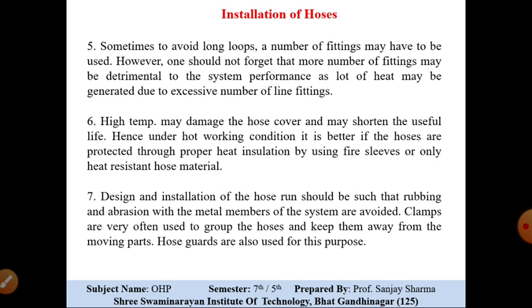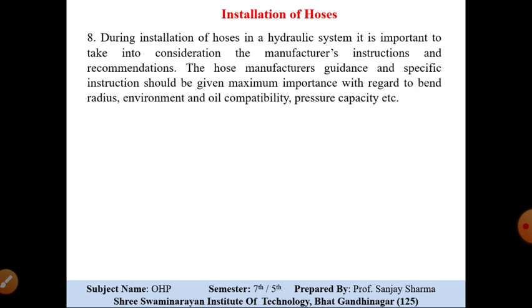So it should be kept in mind that the clamps are used to clamp the hose pipe. They are not left free, and are kept away from the moving parts. The next point: during installation of hose in a hydraulic system, it is important to take into consideration the manufacturer's instruction and recommendation.